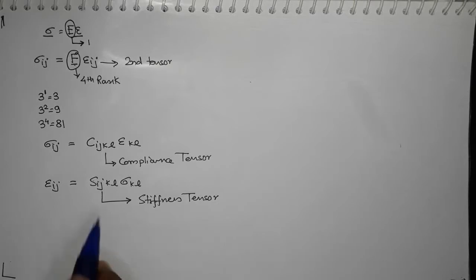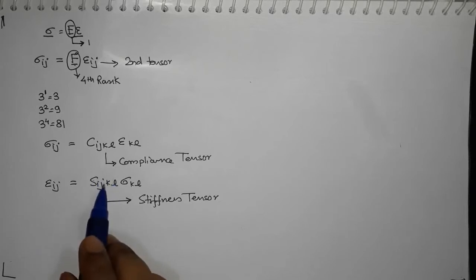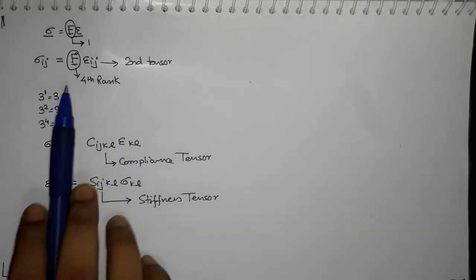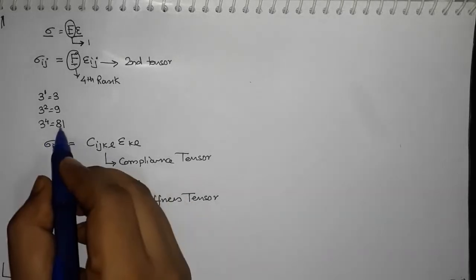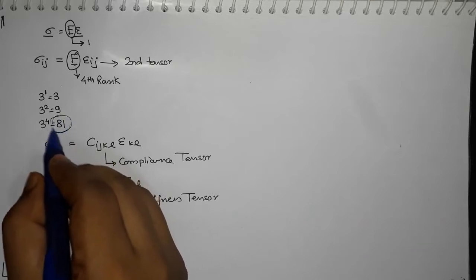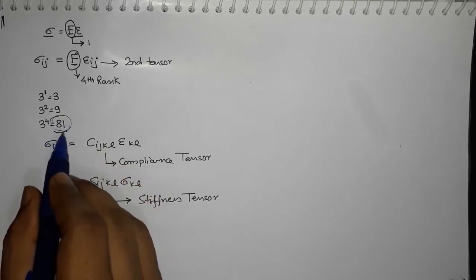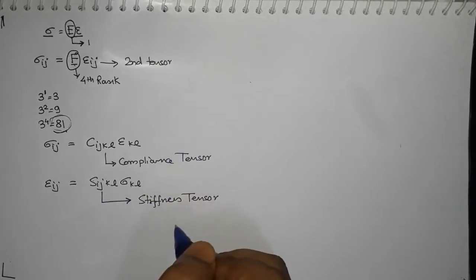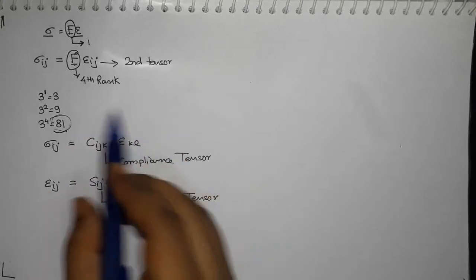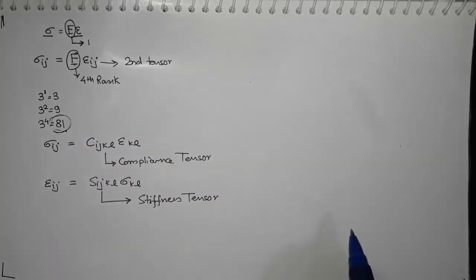so now how do we deal with this fourth rank tensor? So now we know that instead of one value of elastic modulus, we should have 81 values of elastic modulus, right? So is there a possible way to make it a little simpler? The answer is yes. We can reduce the number of components in this one, and we have seen this in our last page, that we don't really need so many values to describe the relationship between a stress and a strain, right?